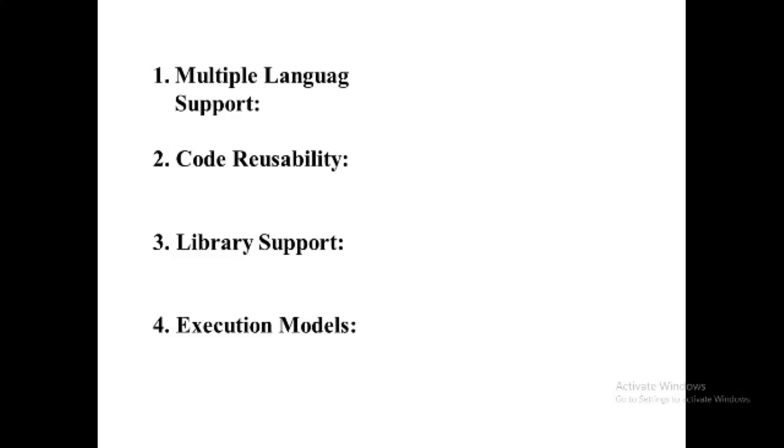By testing early in a project's development, overall project quality can be improved. Installation and commissioning can thus be quicker and less expensive because program faults can be detected and corrected early on during the development.